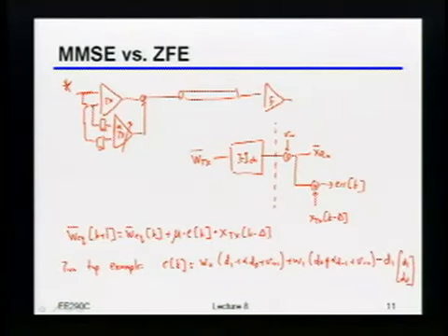Because remember, with DFE, I don't really care about the noise in the first place because there is no noise enhancement. Right? So it turns out that if you're adapting the DFE, this is exactly the kind of update that you would use to adapt the DFE. Because again, in the DFE, you want to make sure that it actually does completely kill the ISI. Okay?